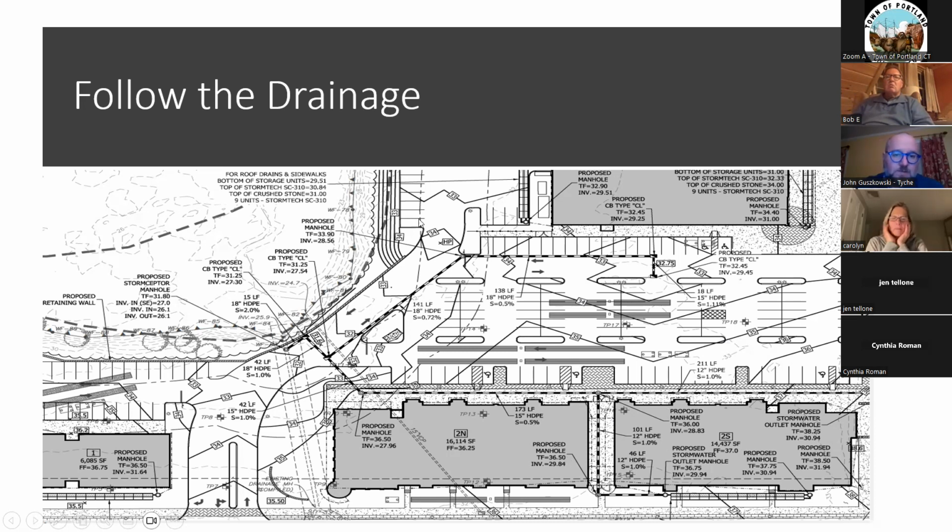And then low points out over here, 33. And then at each catch basin, which is sort of like a terminus or a junction of the drainage, we have the catch basin elevation. So this is at 32.75. Do you see that? Down over here is 31.6. Do you see that? A low point. Up here is drainage at 35.5.